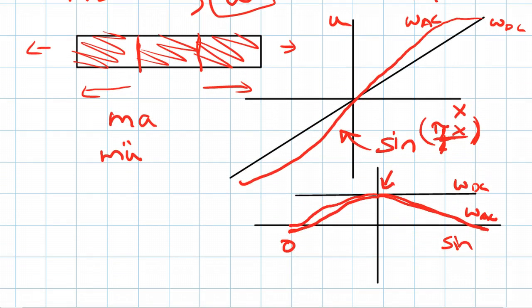Because we have more tugging at the edges, we have more stress in the middle. This is more stressed out because these are pulling on it. So because the middle portion is more stressed, wherever you have stress, you have strain. So S equals s T. Wherever you have the stress, you have strain, a direct relationship. If one is higher, we're going to have a higher strain. So we have high strain in the middle because these have a lot of force putting on them due to the vibration of the outside portion.